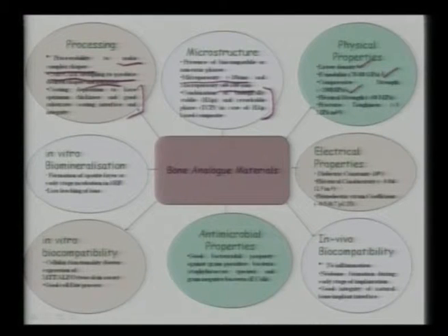For many load bearing applications, compressive strength is important as well as flexural strength. Fracture toughness means the resistance to crack growth, and this resistance to crack growth should be as high as 3 MPa square root meter or more.